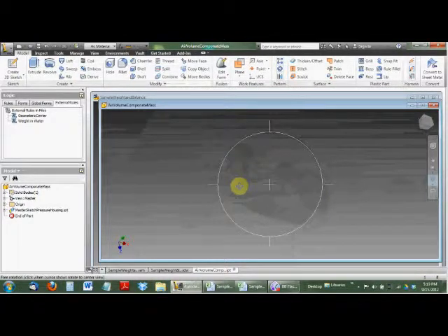So a couple of ways you can, there's some finesse here. First of all, if you have a simple shape, right, it's easy to just make a part that is the same shape and size as the air volume. Now, if you have something very complicated inside the cylinder, like some electronics and circuit boards and chassis and so forth and so on, what you're probably going to want to do is derive this part.